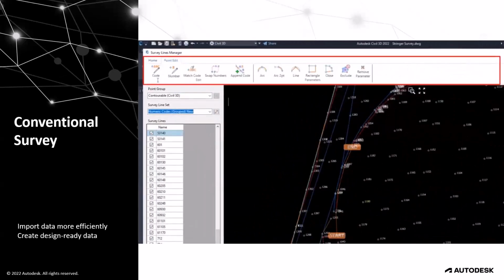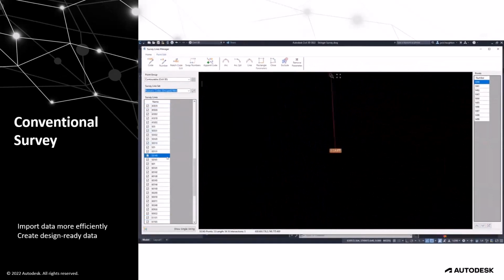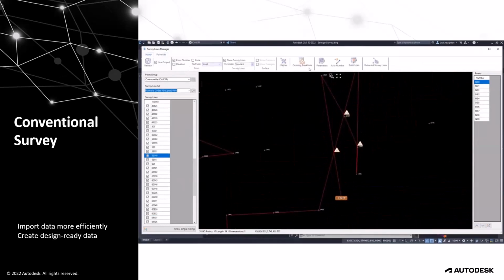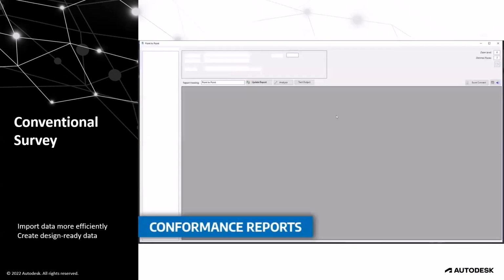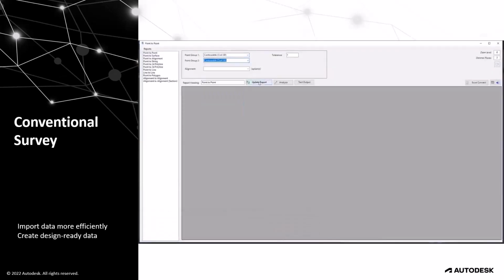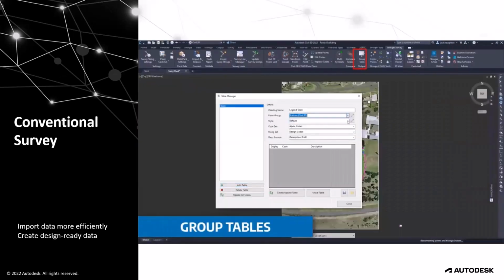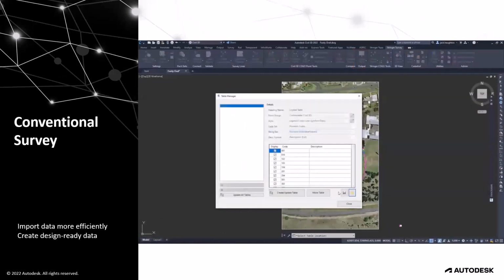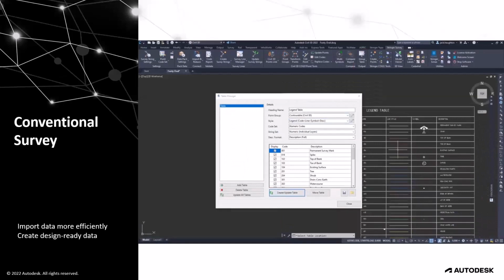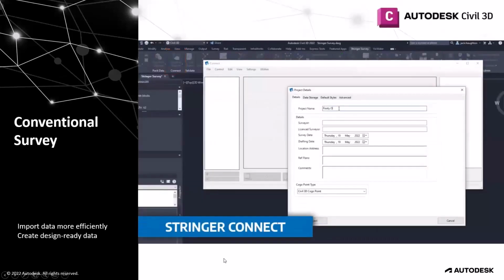So in a topographical survey, you want to quickly get the software to digitize what you've picked up in the field as important asset information. You know, it could be edge of a road, invert of a drain, top of a bank, and certainly there's high-level automation at that end. There's also conformance reporting if you're doing any QA checking as constructed versus designed, and you can certainly publish outputs. So you can see here we're pushing out a typical legend table, but there's certainly production outputs available as well.